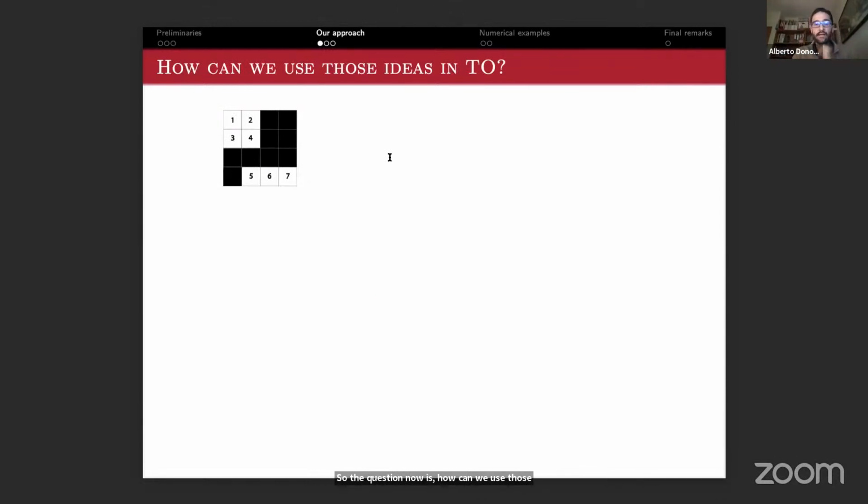We can use these ideas to characterize the connectivity in binary finite element structures like the following 4x4, where black means solid and white means void. Regarding the centroid of each void element as a node of a particular graph, we have the following graph representation. That is, we have two isolated graphs.